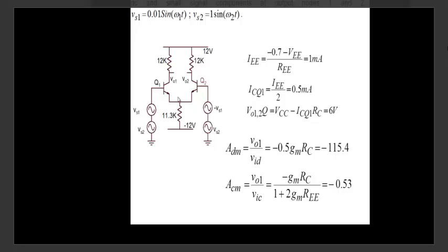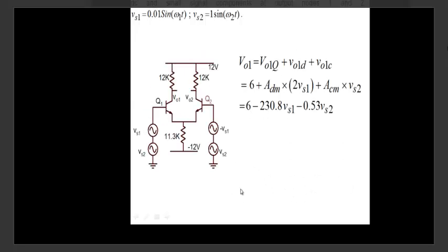You should remember them rather than drawing a small signal circuit in the exam and trying to find out what is differential mode gain and what is common mode gain. Although the derivations are also basically two-step derivations. These are not hard. Anyway, so we know ADM, we know ACM. The next thing is, as we said, we are asking what is the net voltage? Net voltage including DC and small signal components at here and here. So net voltage would be bias point plus a differential mode plus a common mode. So all that we do is, bias point we've already calculated.